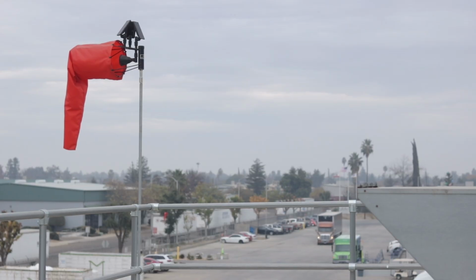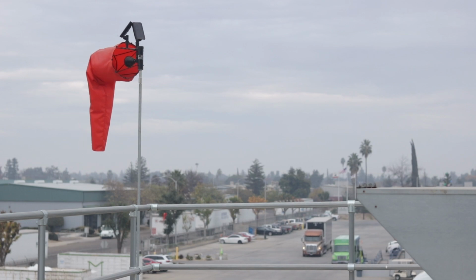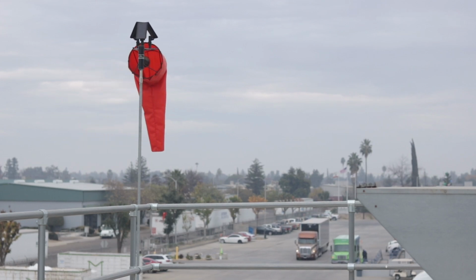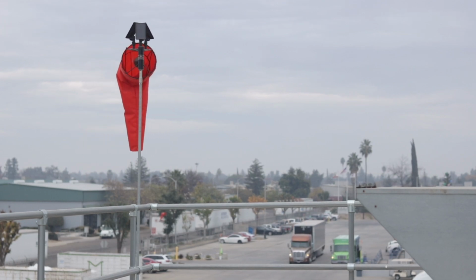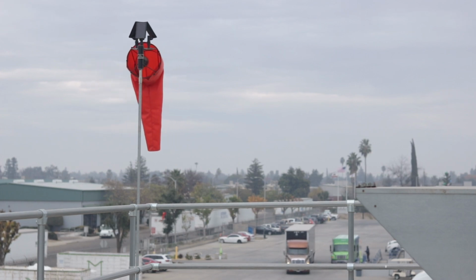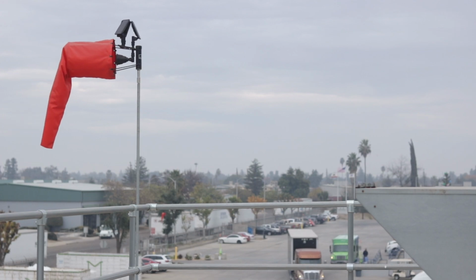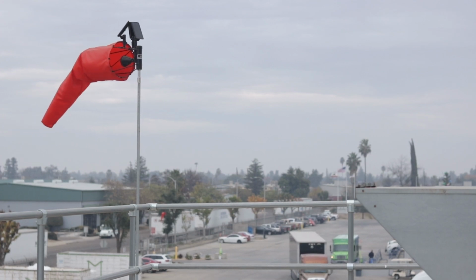Windsocks, typically installed in highly visible areas at a refrigeration plant, indicate wind direction and strength. In the event of a refrigerant release, vapors will travel with the wind. Employees must be trained to locate the windsock immediately to evacuate upwind or crosswind of the release. Always move perpendicular or against the wind direction to avoid exposure.